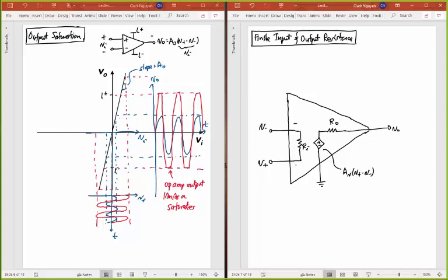And so this is sort of the circuit that I need to use. Right, this is the minus terminal, the plus terminal of my op-amp here, but this is the overall circuit that my op-amp really is. And so when you're simulating an op-amp, and you know its gain, A sub v here, and you also know its input and output resistance, this is the circuit you simulate. Never mind the big triangle outside. This is the circuit you want to simulate. So for that problem on your homework, this is what you want to build in SPICE when you simulate an actual op-amp that you're going to put feedback around. Okay, and I'll let you go ahead and put those elements together.